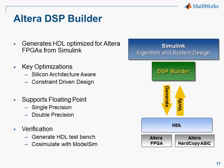DSP Builder is a plugin to the Simulink environment and generates HDL optimized for Altera's FPGAs from Simulink. Once purchased, you will see both the standard and advanced block set. DSP Builder has many key optimizations, such as being silicon aware. DSP Builder ties back to Quartus 2 software for all timing-based information on the device you select within DSP Builder. In addition, there is automatic pipelining to meet the specified Fmax and make latency trade-offs. Finally, DSP Builder provides optimal portability, easily allowing you to upgrade your silicon to future Altera FPGA families.